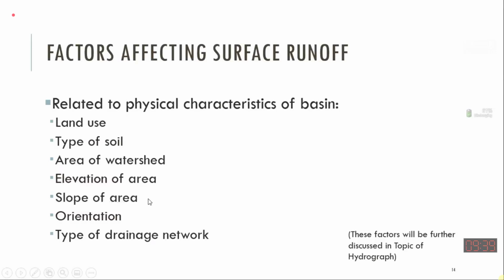When steep slopes are there, surface runoff will be quick and we will be getting a quick response of the stream after the rainfall and after the storm activity. We see rushing streams, high speed streams in the upper area where slope is quite high, and we see calm runoff in the plain area because slope is less.